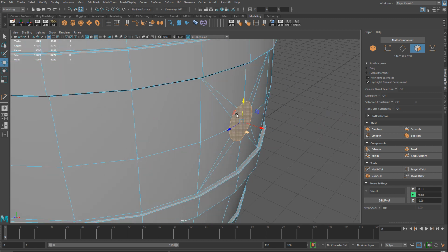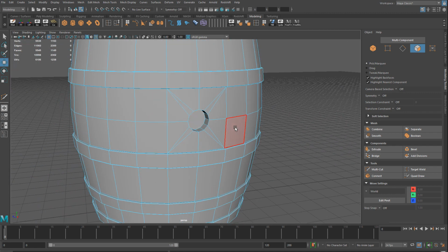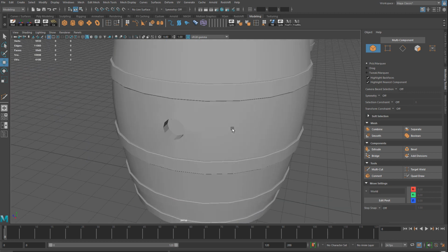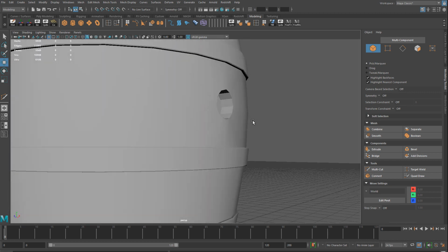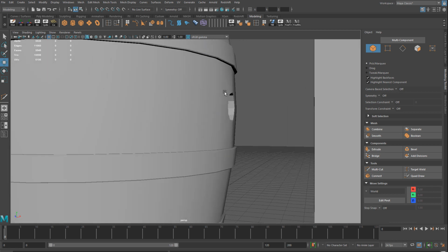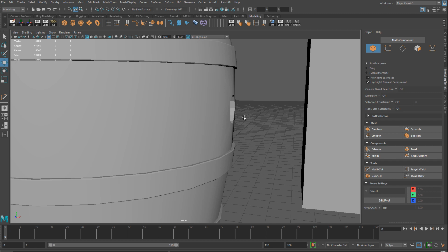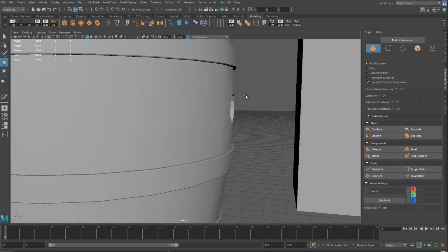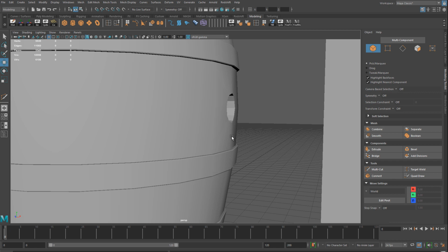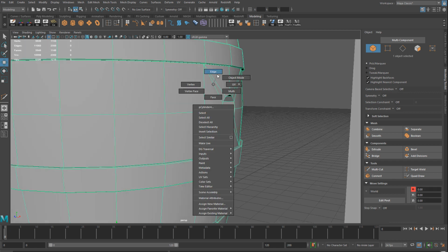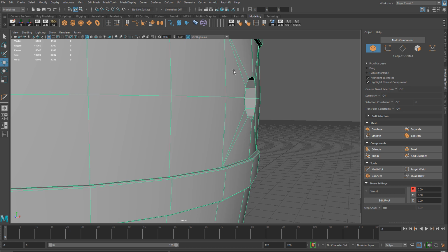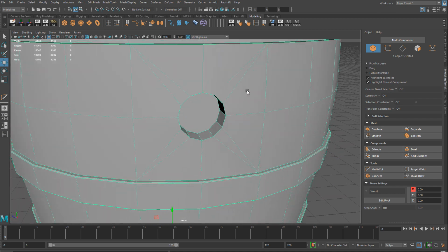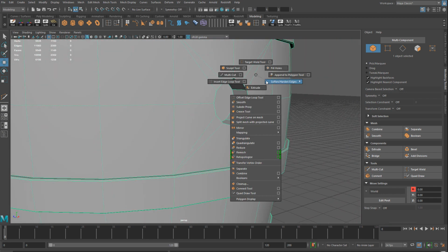Let's take this face and I'm going to extrude that in. Hold shift this time instead of Control E. Hold shift, quick shortcut to extrude. I'll push that in. And let me disable Alt 5. I just want to see if I'm destroying any of the shape. And it's not that bad. I can kind of see it, but through a texture, you'll be able to hide it. There's a little bit of a faceted space right there, just a little bit. But again, I shouldn't be able to see this with the texture. I'm also going to double check my edges. I'm going to hold shift, right click, hold, soften harden edge, and let me toggle soft edge display just to see everything is smooth, and it is. Okay, good. Let me switch it back.